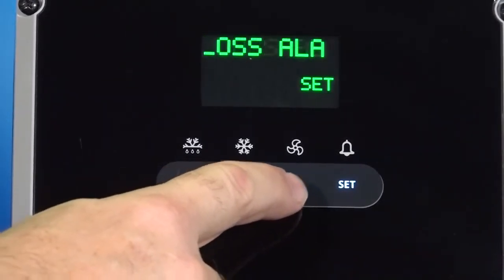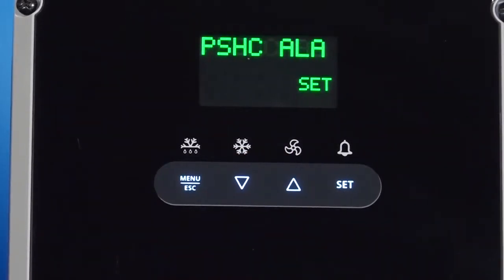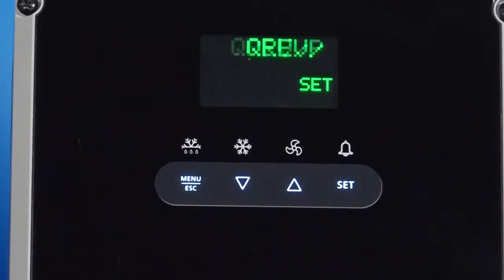There are also 4 other potential alarm conditions that can exist: refrigerant leak, man in room, door open, and emergency shutdown. These last conditions are dependent upon the choices made when setting up the universal inputs. For example, if refrigeration leak and door open are the mode parameters selected when setting up the universal inputs, alarms can be set for both of these events. Man in room and emergency shutdown will not appear as an alarm choice.